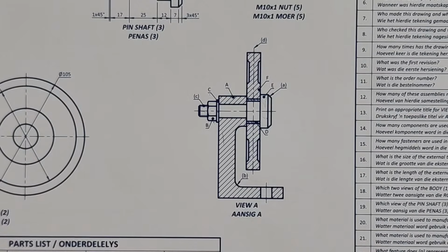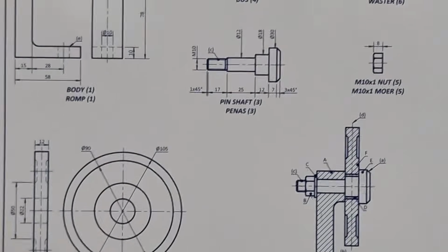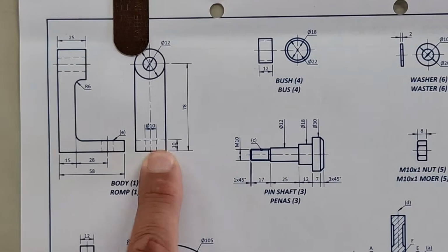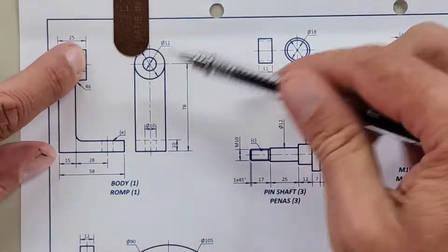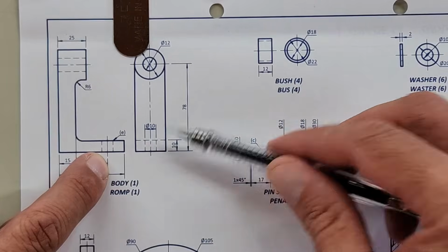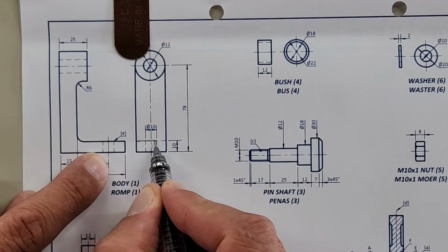Okay, it's third angle orthographic projection. They've given us here the front view and the right view. If I look from the right hand side, I see that circle is that circle. This end is actually drawn wrong here. That must be a solid line.